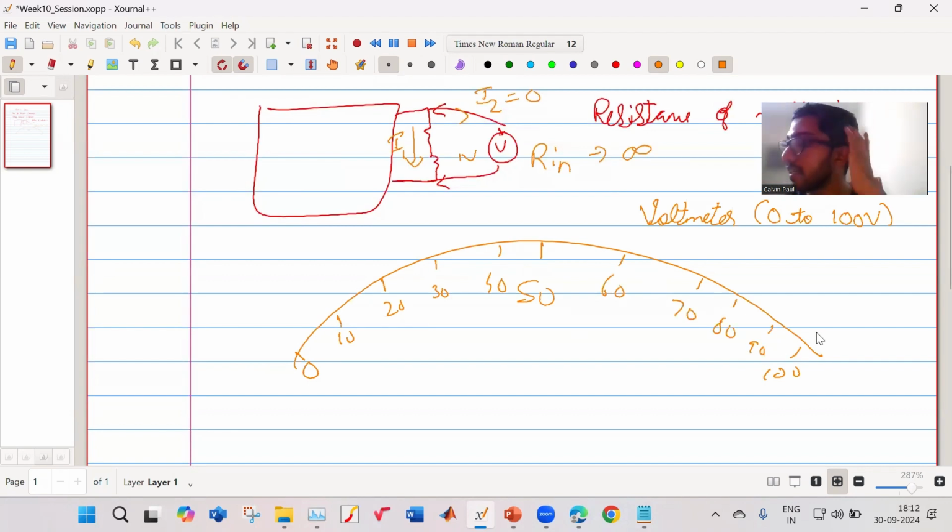It's not uniform, but you get the idea. So 1 volt will be somewhere over here, and when we look at it, we may think it is 2 volt, we may think it is 3 volt. We will not accurately know the exact value. When we look at the voltmeter display, we should look straight, but we may look from some angle. At some angle, it will look either 0 or 2 volt. It is very hard for us to exactly know what the voltage is.